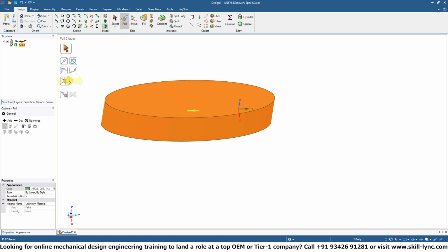If we go into pull and then hit scale body, it asks us for an anchor point. Usually I select a set of axes, or you can put a reference point or dot. This is some unfortunate geometry because as an ellipse it doesn't have a corner or point for us to select, but you can select the set of axes on the body.